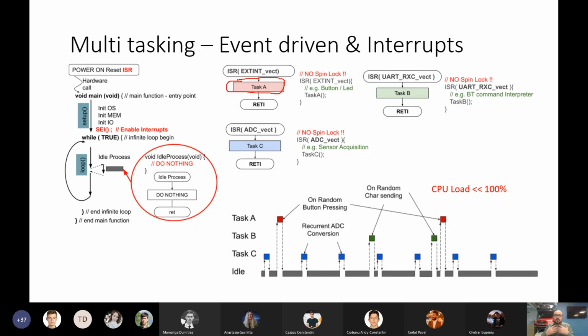How often are we providing some message via the serial interface? Once in a second, once in a minute, once in an hour, 10 times in a minute, but after that staying an hour and so on. That means we will use processing time only when receiving new bytes from the serial interface. Now here the ADC, we can set up to trigger once per millisecond. I don't know how often, but we can set it up.